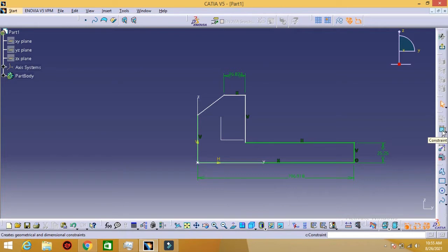It will be clear when I do this task again. So I removed all my constraints. See what happens when I double click here. You press twice on this tool, left click of your mouse. Double. So it became permanently active. How do I check? I click this line, drag it outward, do left click, and I got my dimension value, whatever is the dimension here. But still the tool is active. If I click it now, it will be deactivated.